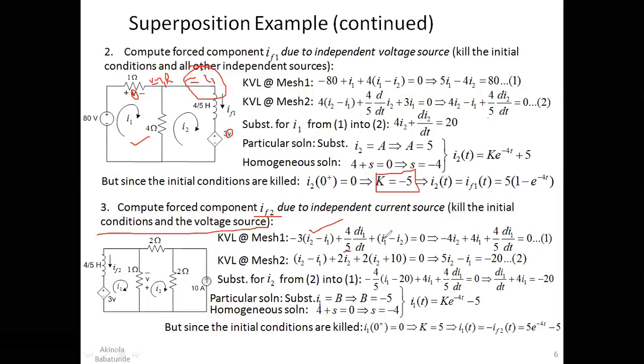All right. Now you add everything together and then you equate to 0 according to KVL. What you would notice here is that our IF1 in this case is not going to be equal to I1. Why? Because they are in opposite direction. So our I1 would automatically be equal to minus IF2. Whatever we get as our I1 would be negative of it because they are in opposite direction. So I1 would be equal to minus IF2. I just wanted to point that out before we continue.